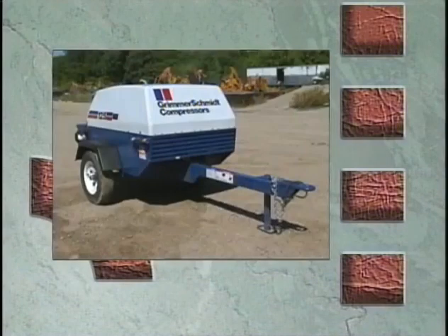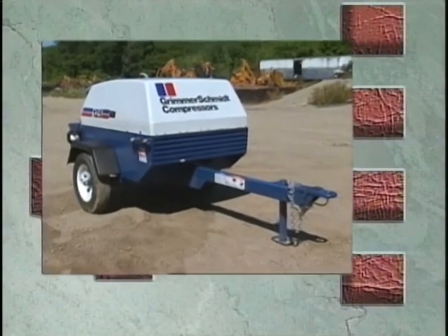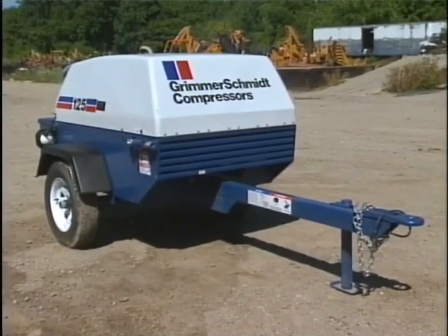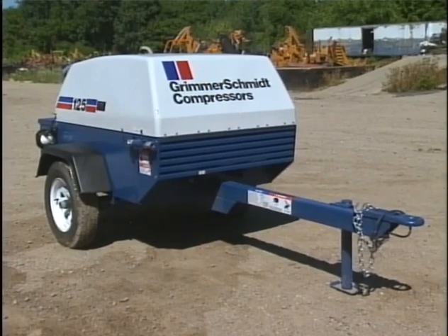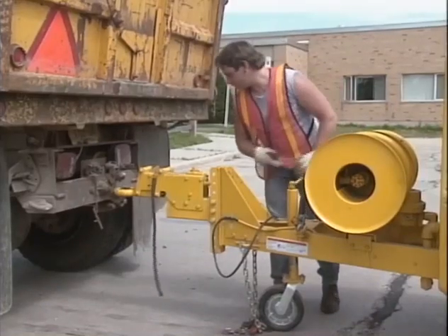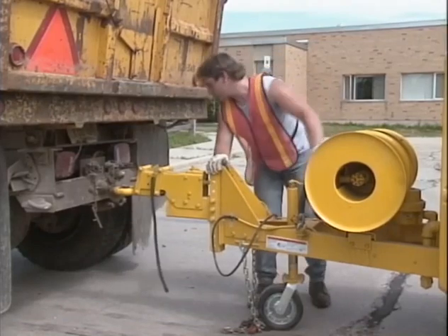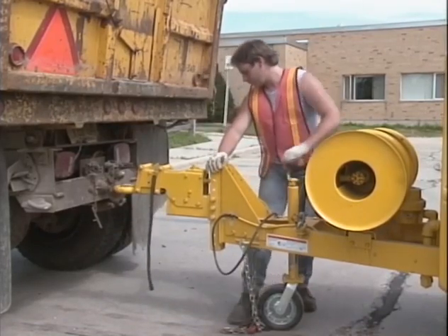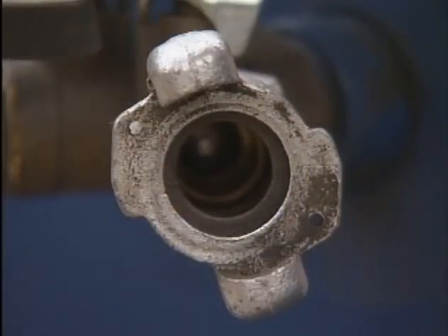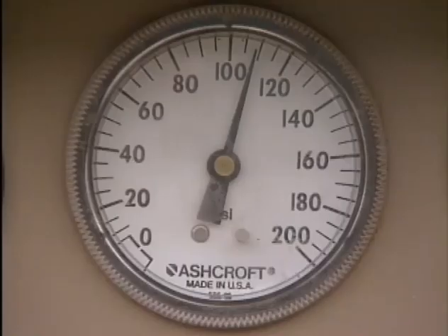Work safely. Beware of lightning. Stay clear of the machine during electrical storms. It can attract lightning. Safe working procedures. Do not attempt to move the compressor or lift the drawbar without adequate personnel or equipment to handle the weight. Keep personnel out of line with or away from discharge openings at valves, couplings, or hoses. Do not exceed manufacturer's air pressure rating.